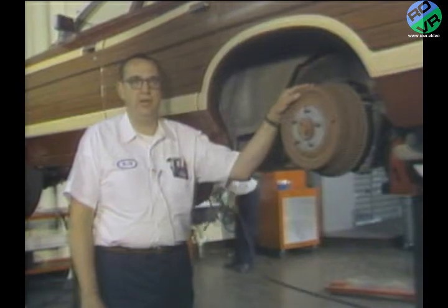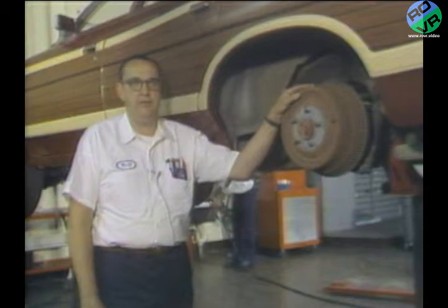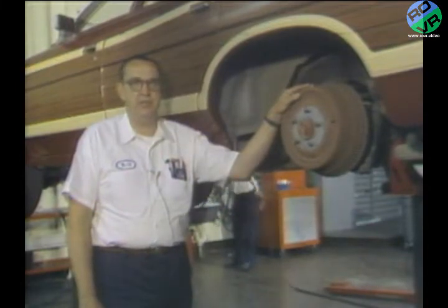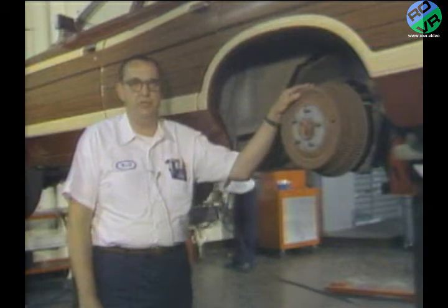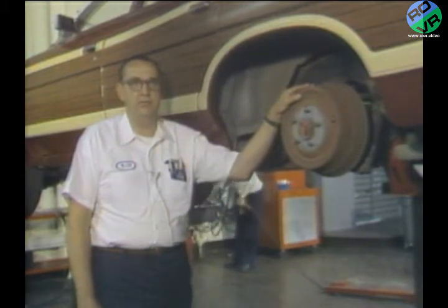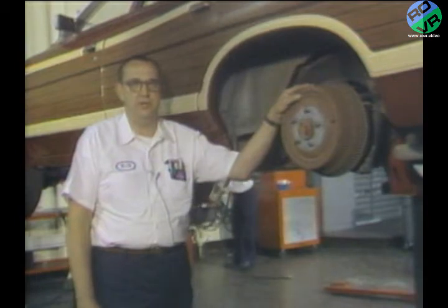The purpose of operating the vehicle without the wheels is to further isolate the driveline problem. If vibration does occur at the same engine speed noted during the road test, the problem is definitely with the driveline because no wheels or tires are present to cause vibration.